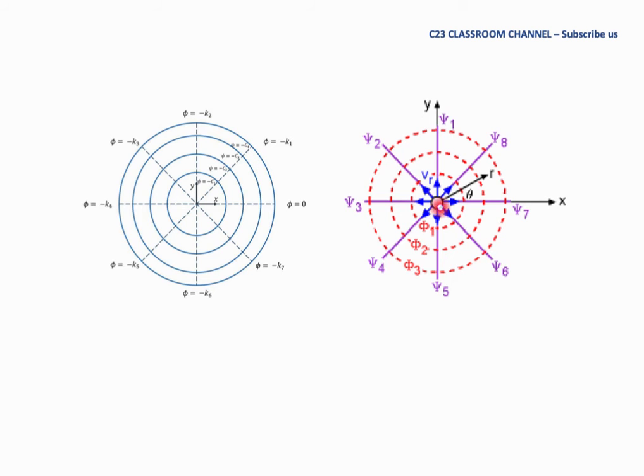So again, if we have a real situation where fluid moves from one point here in a radial direction like this, moving outward and parallel with the radius direction, it means that the flow from the origin here parallel with the radius here will become the psi, or the stream function, the streamline, because streamline must reflect the real flow of a certain fluid.